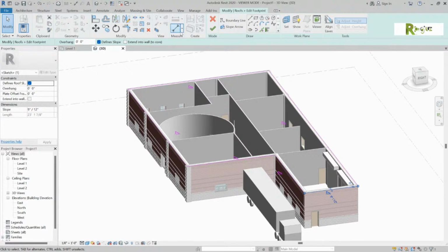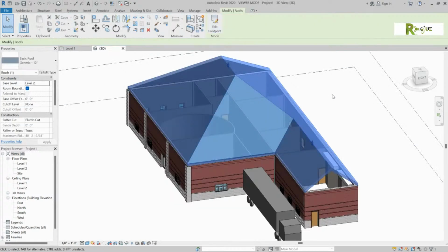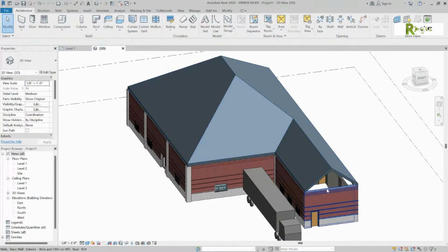There's a checkbox that says define slope. Below it, down just a little bit, it's between our tag. That's it. Right on that bar. Look over a little bit. Take the define slope off. Okay. And say okay. And you're going to see that now that one piece of the roof is not sloped, it's gabled.